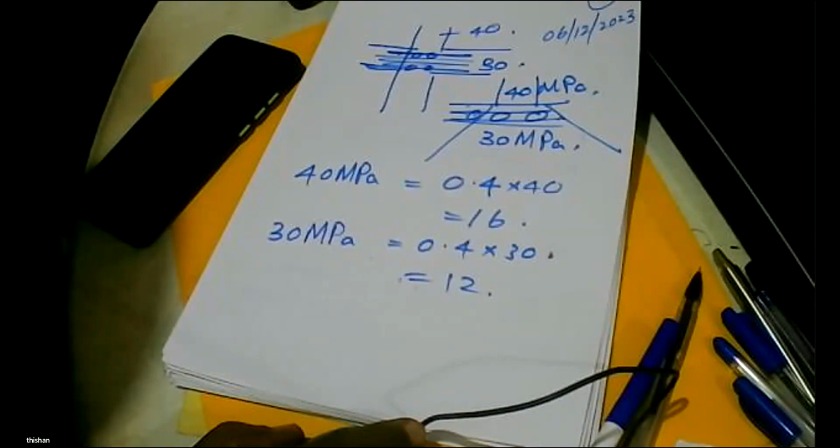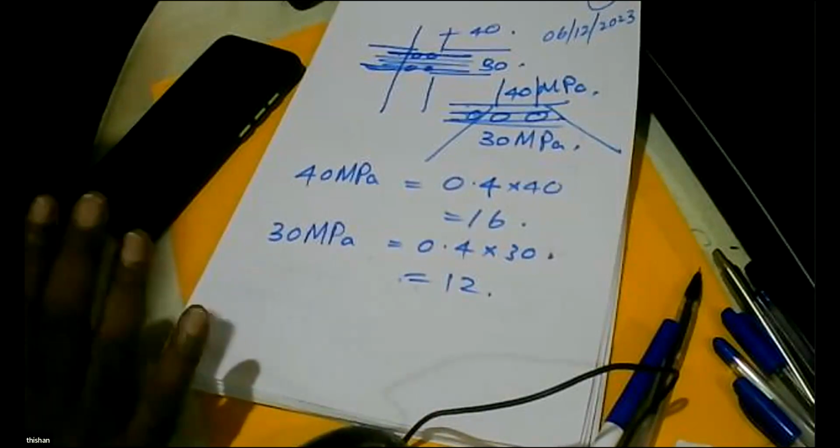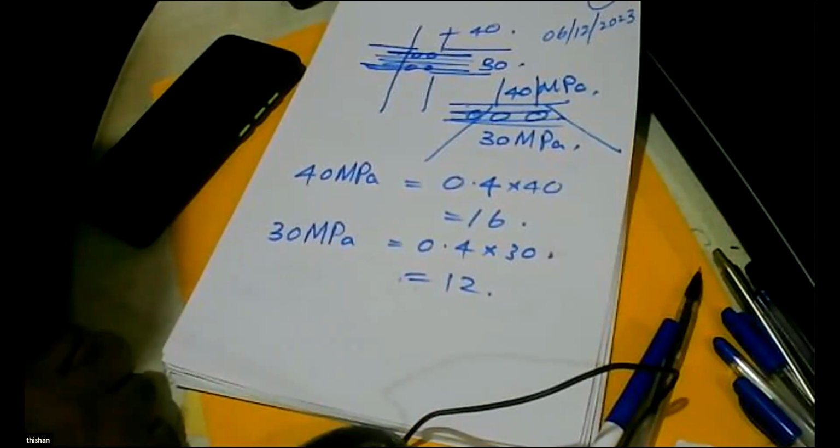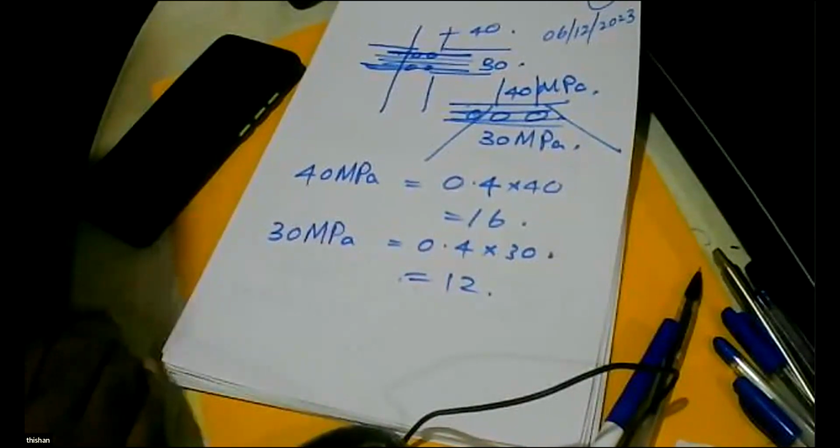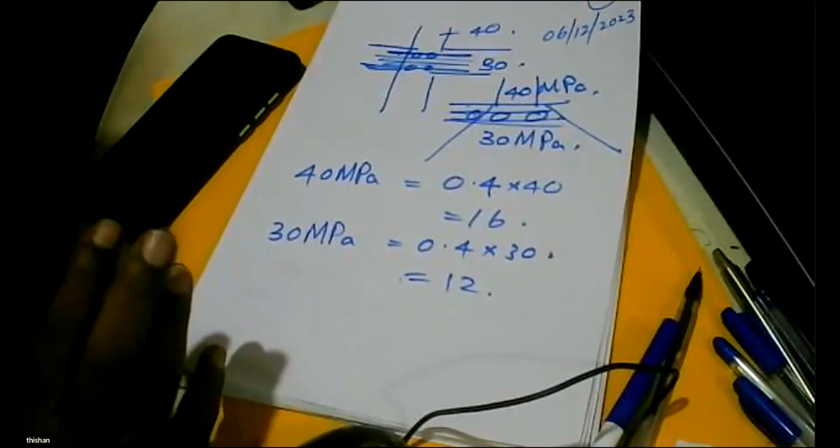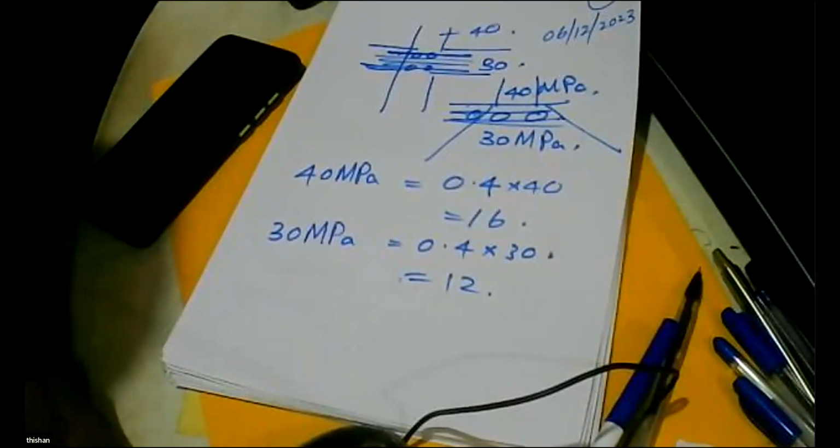No. A huge amount of research has gone into concrete mix design, because nobody could get it right. Because of that, I developed a simple method, which is purely based on logic. That's why I showed you how I manipulate the numbers. I know only two things. One is that cement is the friend. What is the enemy? I manipulate the enemy. The moment I manipulate the enemy and make it as small as possible, I can bring the cement content down drastically.